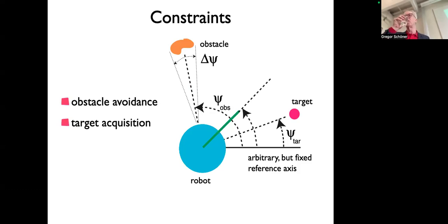The world reference axis, is it fixed on a point, or is it always on top of our robot and just points always in the same direction? In practice, that axis is implicit in the code that you're writing, so we will not typically calibrate it. In many cases you don't even need to estimate your current heading, but under some circumstances you need that. When you put the robot down in the world, there will be a world axis. Depending on how you coded that, it might be an axis that's orthogonal to the initial position, or it's ahead. It depends on how you wrote down the code, where your angles begin and end.